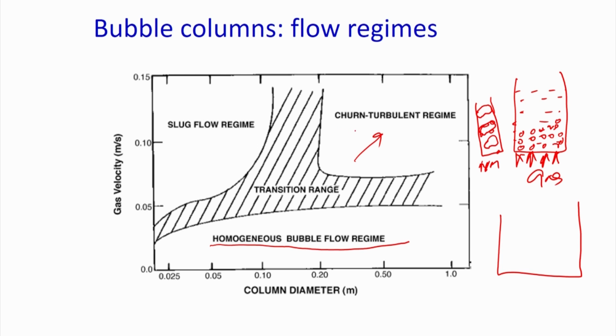There will be some tiny bubbles, some bigger bubbles which have been formed by coalescence, and then those coalesced bubbles will actually break into 2 smaller bubbles. So, we will see all kinds of chaotic dynamics inside, and a very wide bubble size distribution. Most of the industries operate the bubble column for reaction purpose, again, I am quoting, for reaction purpose, under the churn turbulent flow regime to achieve higher yield.